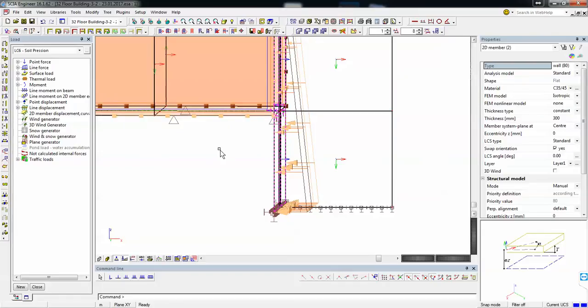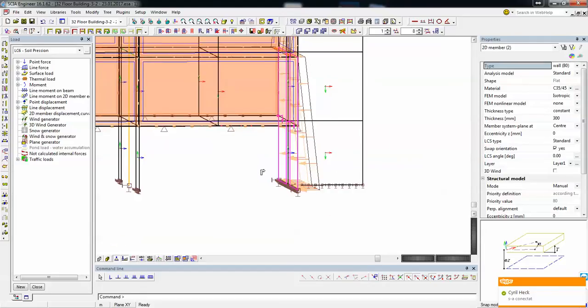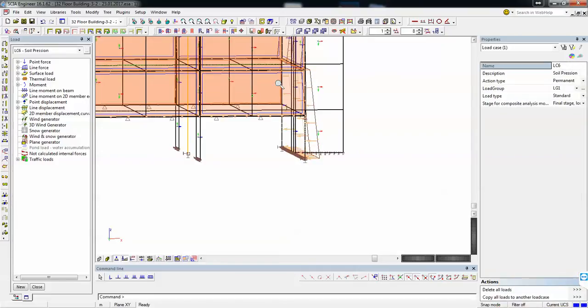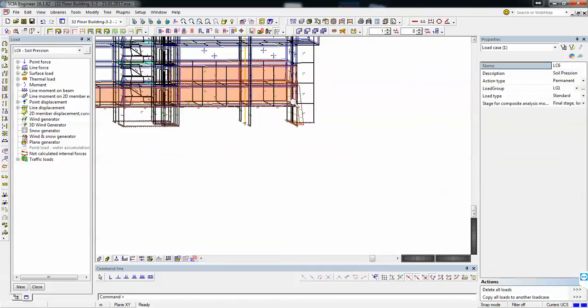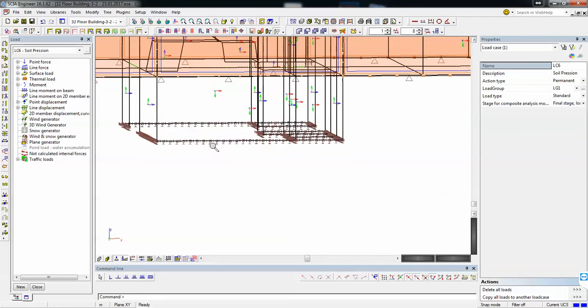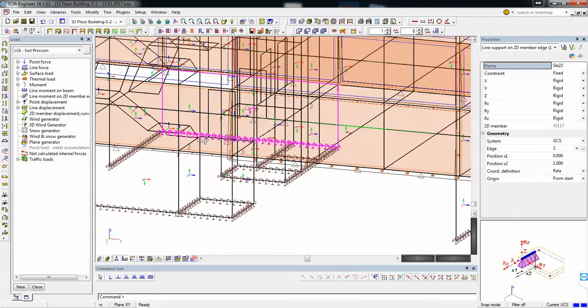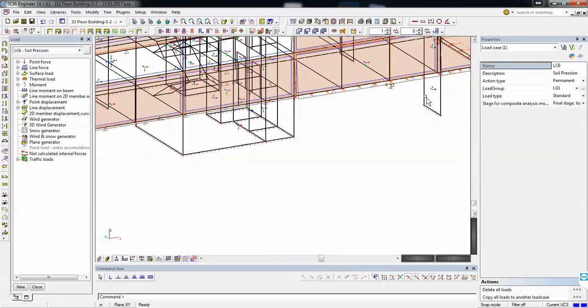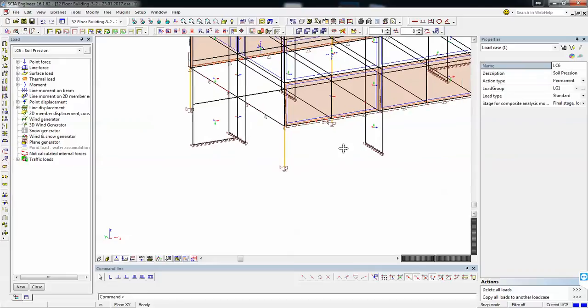You understand? On the left side, there's also soil, so there's no pressure, because even if it's in the ground, we have pressure on both sides, so they cancel each other. So you only need pressure on this part, where you have an opening inside and people live there, and also on this side. Everywhere you have a basement, you have pressure, but if you only have buried structure, there's no pressure there. You understand?